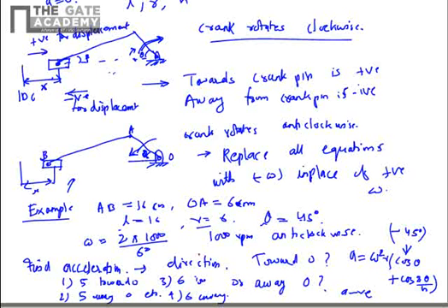So I am leaving the numerical calculation part here. That is pretty much straightforward. You have to just put the value of n, theta, and omega in this expression and get the answer. For the direction, if the acceleration is negative, it is away from crank pin. If it is positive, it is towards the crank pin. Like that, you can get the correct answer.